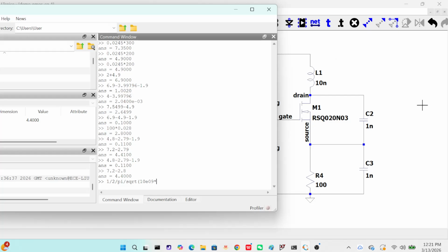The capacitance here, we find the equivalent of this, so it should be 0.5 nano. So I got 70 megahertz. It's obviously too large. You will not get any good oscillation. You will get the oscillation, but the amplitude will be very low.